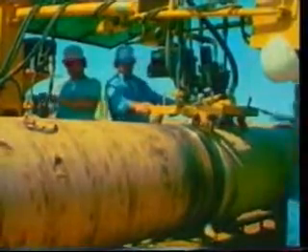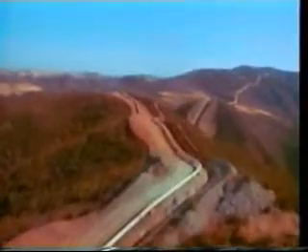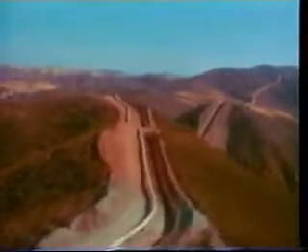Fittings are manufactured to be threaded, welded, or flanged into place. Threaded fittings are available for most materials and pressure ratings. Welded fittings are common and readily available for the applications just discussed. Since most fittings are installed permanently, welding is often used. The difference in pressure drop through threaded, welded, and flanged connections is not significant.